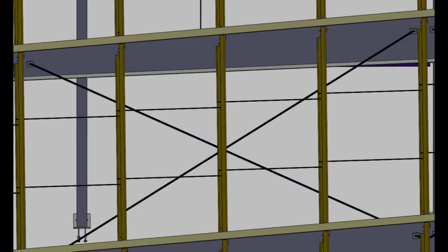This view clearly shows the wall X-bracing system of the PEB structure. Two diagonal bracing members cross each other to form an X-shaped arrangement within the selected structural bay. This bracing system contributes to the longitudinal stability of the building and helps transfer lateral forces through the structural framing system. The horizontal wall girts and surrounding vertical framing members are also visible. Together, the wall framing and bracing system form an important part of the overall stability arrangement of the PEB structure.